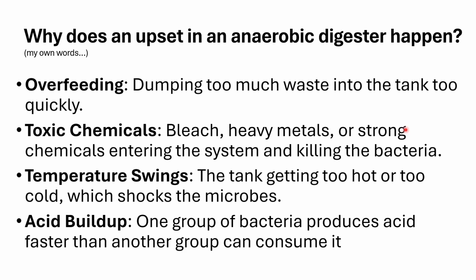Even Bueno chili, like I talked about, if they dumped a bunch of green chili peels and stems and seeds into the wastewater collection system, well, that's all got a chemical called capsaicin. That's what makes the chili hot. You get that into the digester, it's going to kill off some of those microbes. So toxic chemicals can cause us a problem. Overfeeding, toxic chemicals, temperature swings. We're shocking the microbes. If we go beyond that 1 degree Fahrenheit rise or fall per day, we get our microbes shocked. We get them sick. They don't want to eat.